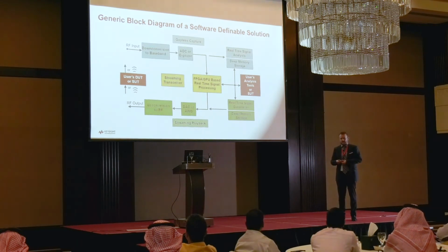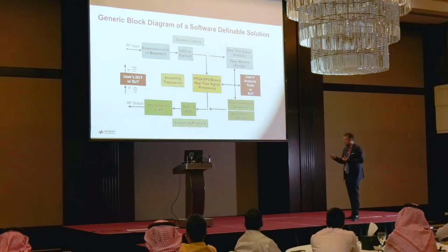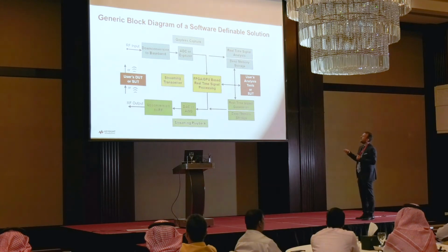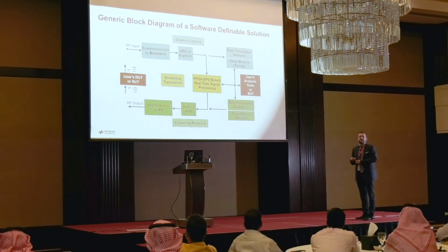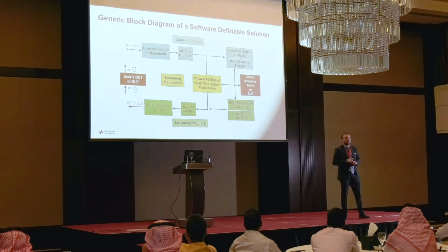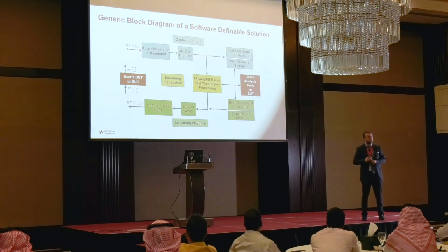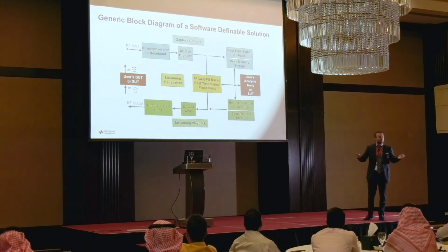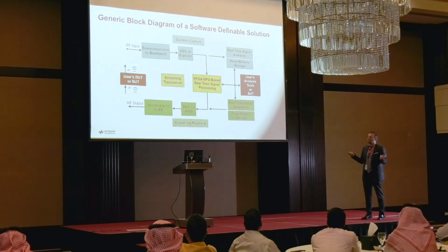Phil mentioned, and I've mentioned already, this wideband signal platform. You can see the component parts of this: down conversion to baseband, wideband, high-speed ADCs. We're talking about real-time data acquisition at up to around 12 gigahertz sample rates. So we can capture very wide signals. Once we've captured those signals, we can do a number of things.